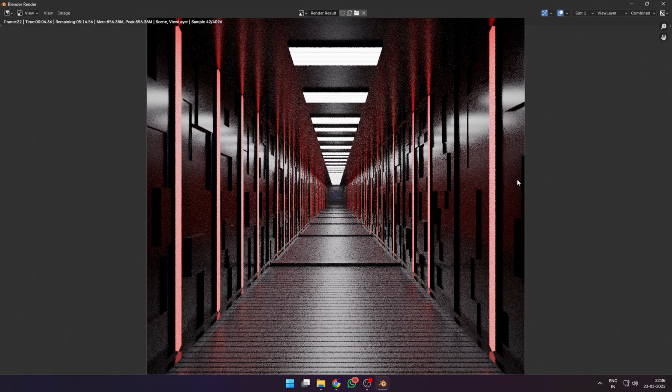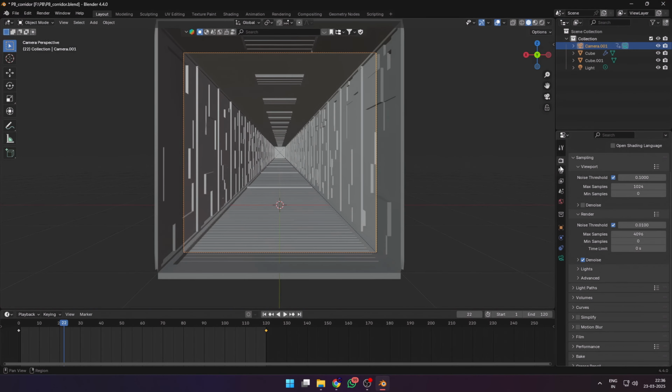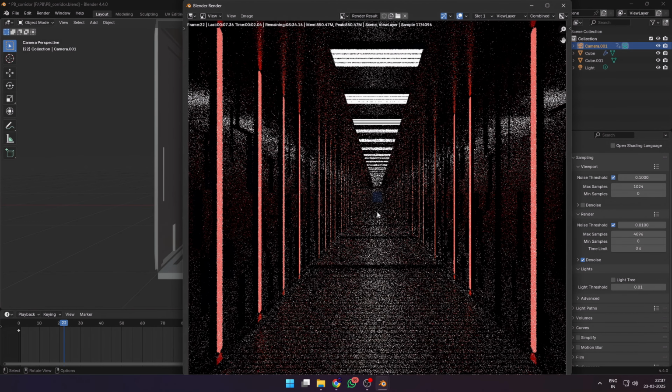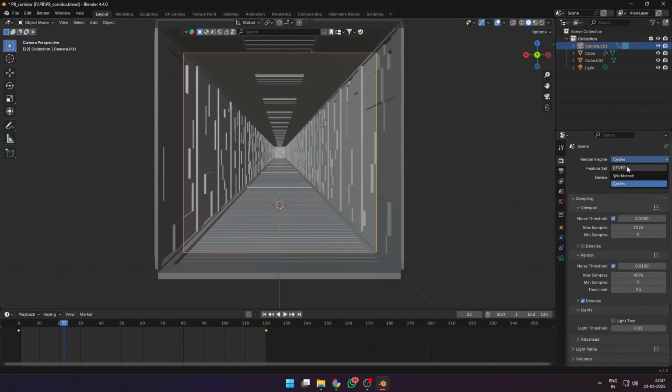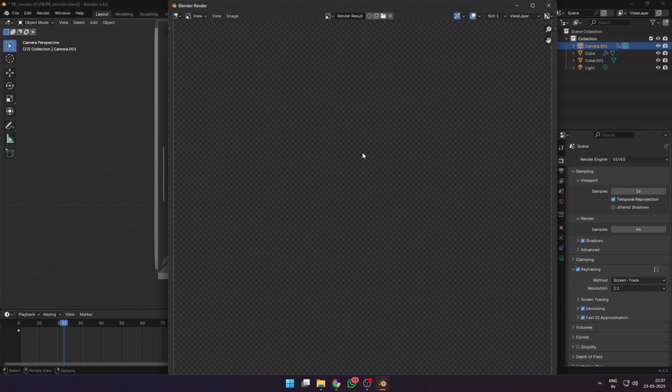Whether you're in Cycles or Eevee, you need to set the render samples. Render samples in Blender determines how many times Blender calculates lights per pixel in an image. If you're working with Eevee, the default render size of 64 works, but in Cycles, it's usually 4096, which is a very high number, so you can reduce it to 100, 200, 400 samples as your scene requires. When you're in Cycles, make sure to turn off the light tree option under lights in the render settings for faster renders. And if you're in Eevee, make sure to turn on ray tracing for more realistic renders.